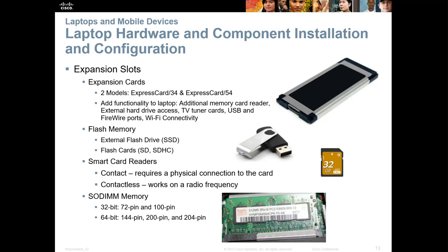SODIMMs can be further classified as DDR, DDR2, and DDR3, and some laptop models require different types of SODIMM. So before you purchase and install RAM, make sure you consult your laptop documentation or the manufacturer's website for your form factor specifications, and for documentation on where to find and install RAM on the laptop.